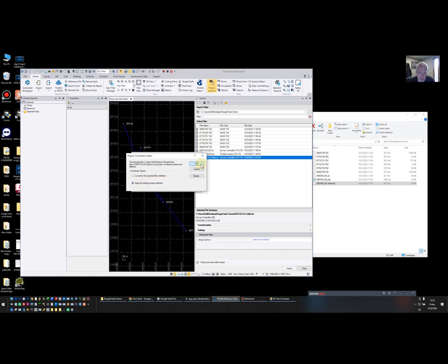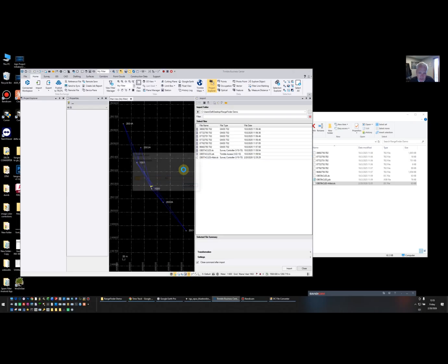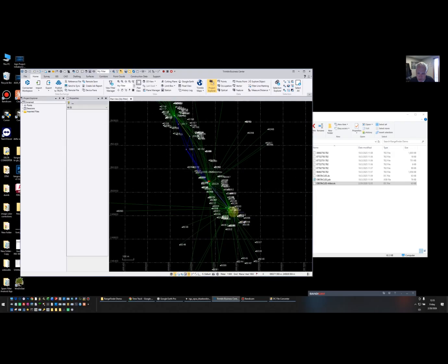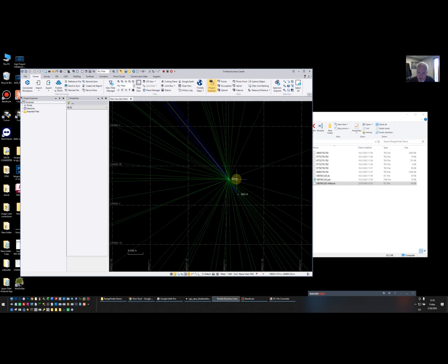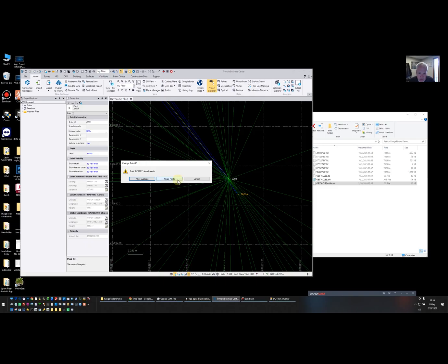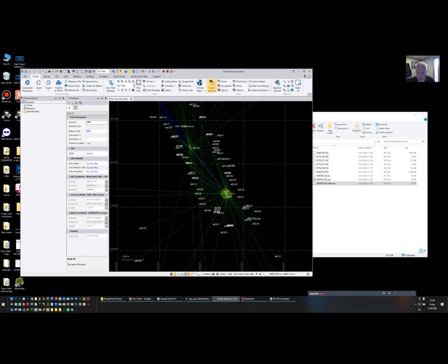Keep the existing project definition. And there you go. Now, we typically shoot 2 points, so we'll shoot a 2001 as a control nail, and then we'll rotate the tripod 180 degrees and shoot a second one. So we'll have to go through and rename that A and merge those points. But that's all there is to it.